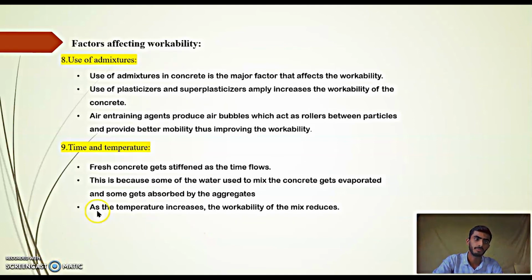Next is admixtures. Admixtures also play a vital role in the factors affecting the workability. Use of admixtures in concrete is a major factor that affects the workability. Use of plasticizers and super plasticizers increases the workability of the concrete. As we know, we apply retarders, plasticizers and accelerators to increase or decrease the workability of concrete. It depends on the weather and the type of condition in which we are constructing the work, and we have to use plasticizer, accelerator or retarder, etc.